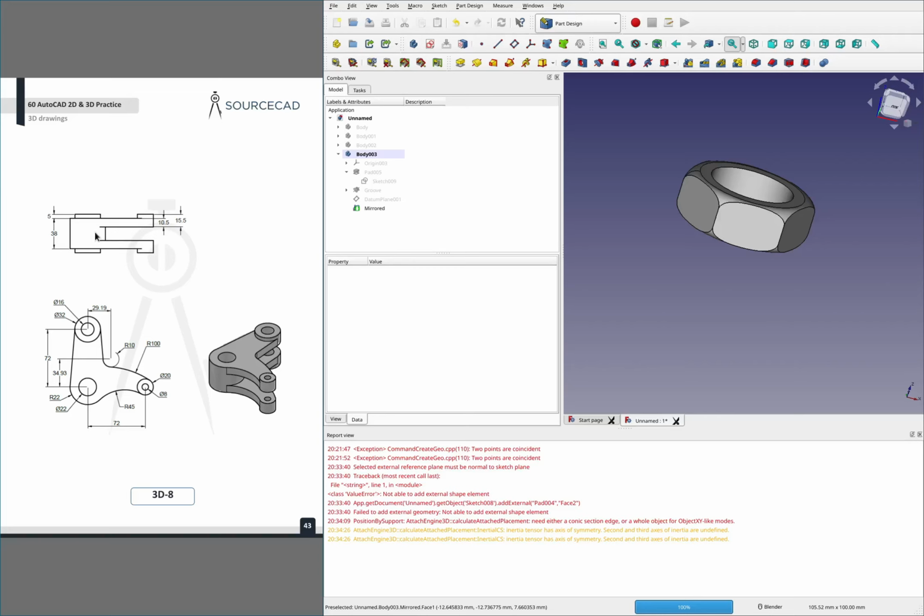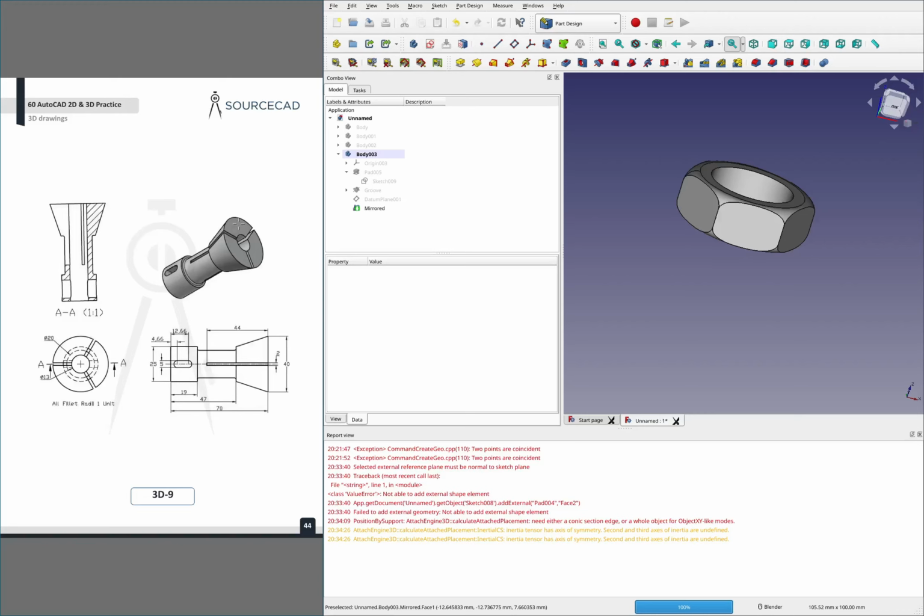So what I would do is start with this kind of funky face, and extrude that, and then you've got this cylindrical bit, and then after you do that, you can extrude these two upper parts, and then you can mirror the whole thing over to the other side. And I guess we're just supposed to assume that it's mirrored because these bits here aren't actually dimensioned. But other than that, relatively straightforward. So we'll skip that one.